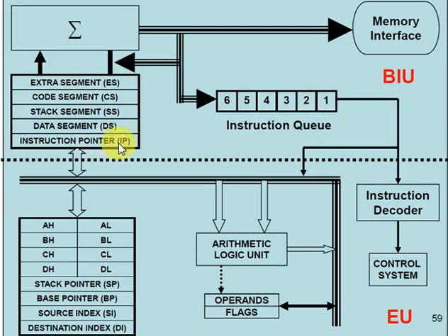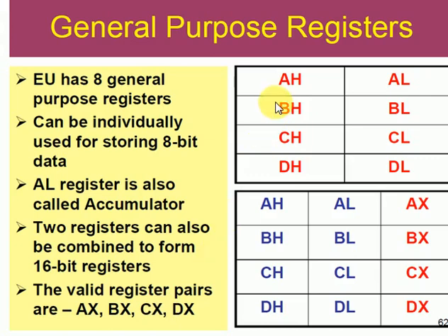the stack pointer. It can identify the address of the next instruction. So again, the 8086 microprocessor can support the pipelining concept by using an instruction queue. Here a 6 byte queue is used in the 8086 microprocessor. It has four 16-bit registers: AX, BX, CX, DX, and each 16-bit register is divided into two 8-bit registers: AL, AH, BL, BH, CH, CL, and then DL, DH. You know very well, L is identified by the lower order byte, H by the higher order byte.